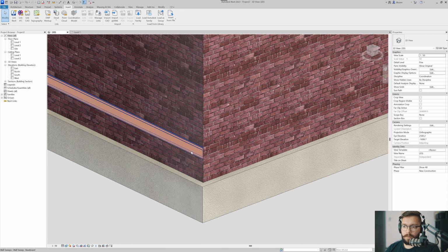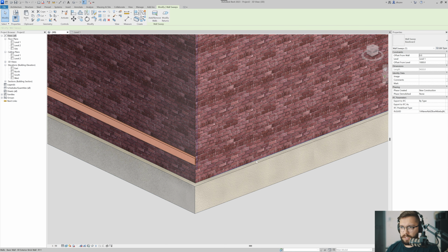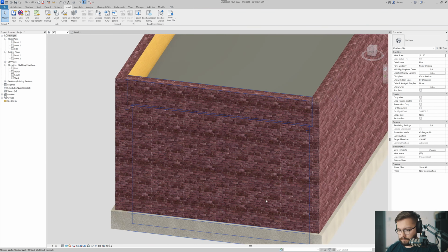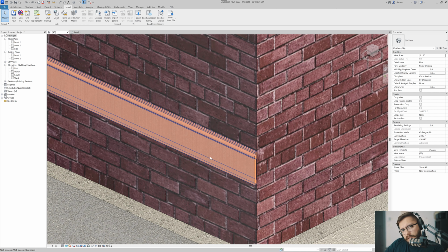And so that means that, first of all, your elevations would look a lot more realistic, straight out of the gate. And your renderings too. It's very rare that in real life you just have a wall hit a floor, like in museums maybe, and even then maybe a reveal would be that transition. But so I can select it, add, remove walls, and just add it and keep on going around. Where is it? Boom.